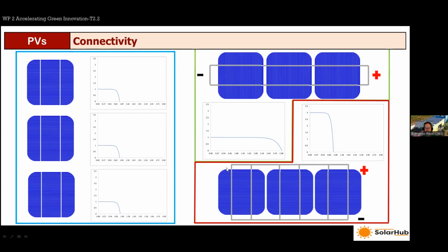Of course, I have to be very precise in terms of using this topology. This is not usually how photovoltaic modules are designed. You will most probably see strings of PV cells in series rather than parallel ones, because it's easier to have higher current from one cell, and it's harder to have higher voltage from one cell.